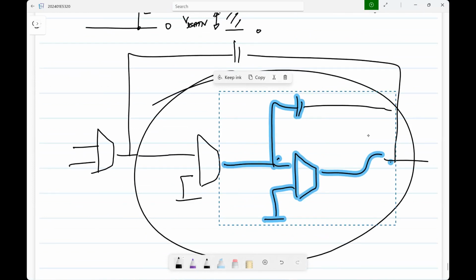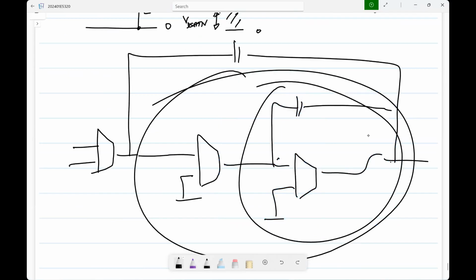Roughly speaking, what's the DC gain of this? It's basically a product of 3 stage gains. So you can get, I've seen up to 5 stages also. Normally you don't do it, but you do it only if necessary. But it is possible. But the point is not to think of all these things as like different circuits, right? You're improving the I to E conversion, and as and when you make better op-amps, you could probably use them in place of that ideal op-amp.